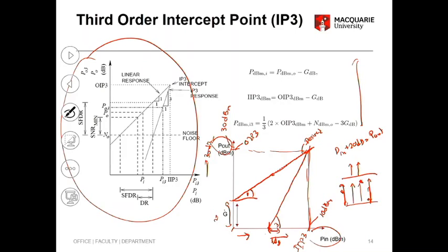So now the questions that you, so that's what this curve's about. So the IIP3 plus G, which is 20 plus 10, gives you 30. This is pretty much saying 10, that's 20, and that's X, right? That's what you did. X equals 10 plus 20, which is 30. So you don't really need to use the equation, you can just work it out from the graph.